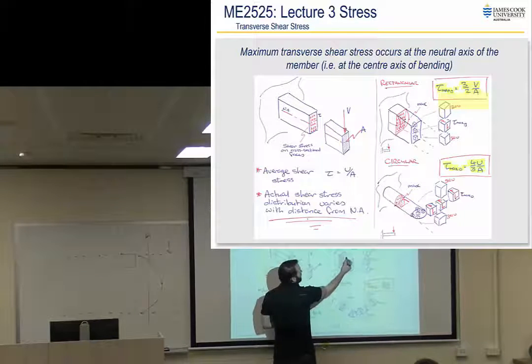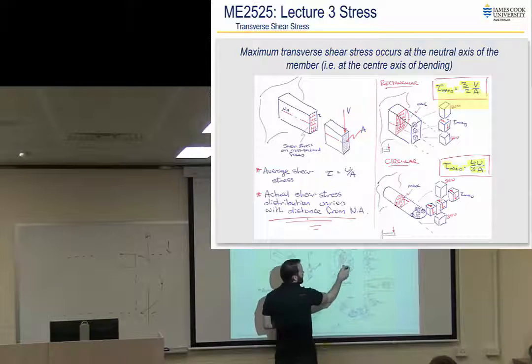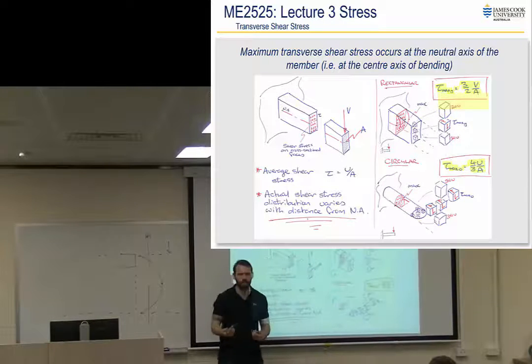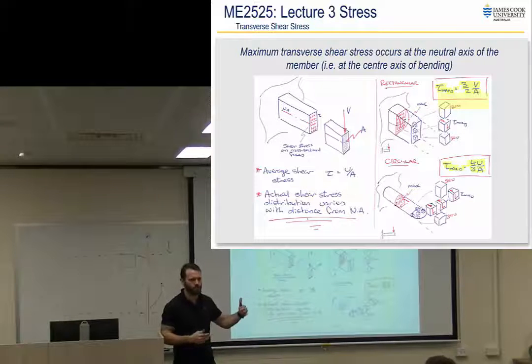Anywhere along that plane there, I could get my stress element. Anywhere along the top and bottom, I'll have a 0 stress element. And anywhere in between those things will be some combination of both. But almost always that won't be a critical place. You'll either have a critical in the middle or critical in the top and bottom, depending on bending and torsion and that sort of stuff.